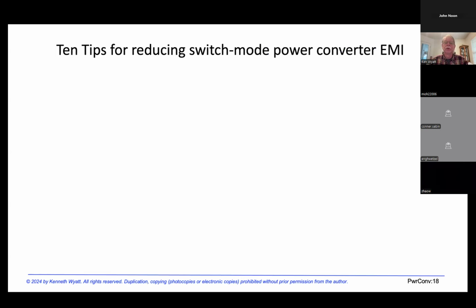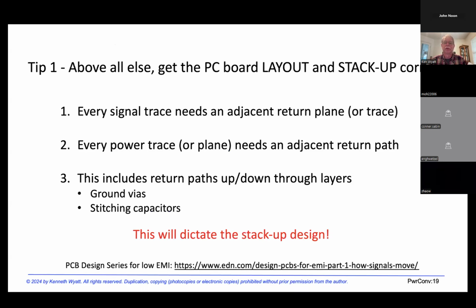In this last half of the talk, I'm going to give you 10 tips for reducing switch mode power converter EMI. The first tip is PC board layout and stack up.